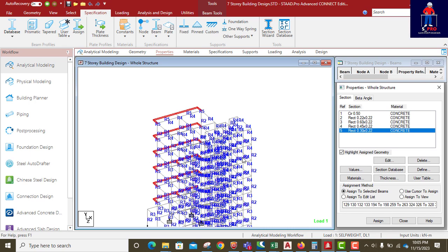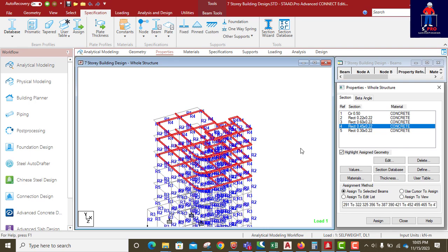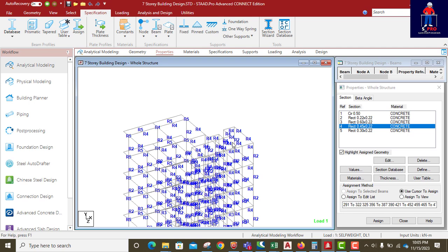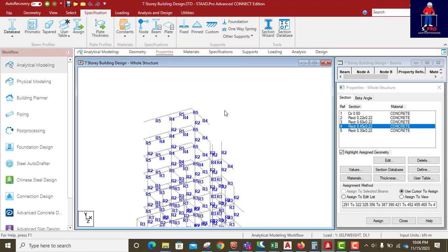When we pick a floor and design, every one of these floors has the cantilever. So we are going to be designing the cantilever beam there. Once we pick a particular floor, we design them together. But we are also going to pay special attention to this last level where we have our water tank. We need to design it as well to see if the roof beam there can withstand the point load which we applied. If the beam is failing, we will quickly increase the depth.